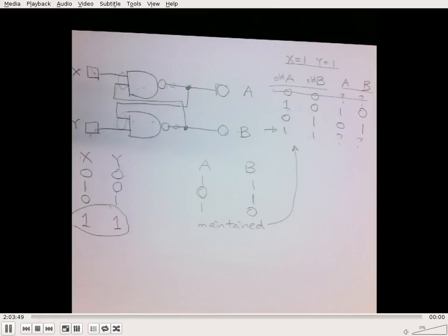In this scenario, the lines to the output are actually shorter than the lines back to the input. So would your outputs also oscillate in that case? Yes. So A and B will both go from 0 to 1 and both go from 1 to 0 at exactly the same time. But that depends on the gates being completely identical, with no difference between the propagation delay. So how do you simulate a race condition in LogicSim?